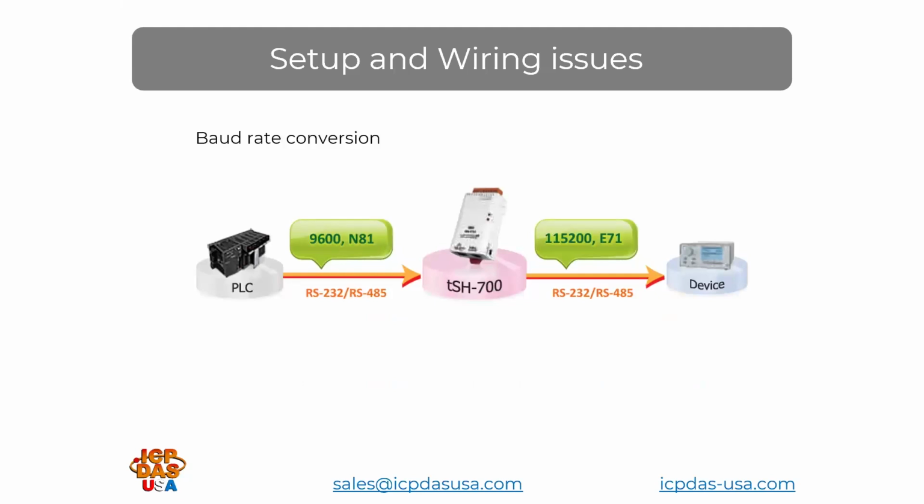An RS-485 port is a COM port. The RS-485 baud rate and parity is set during installation. All slaves must have the same baud rate and parity option to communicate. Once in a while, there's a slave device which has a fixed baud rate and parity option, which will cause error issues. The TSH series, shown here, the TSH725, for instance, has two COM ports, one incoming and one